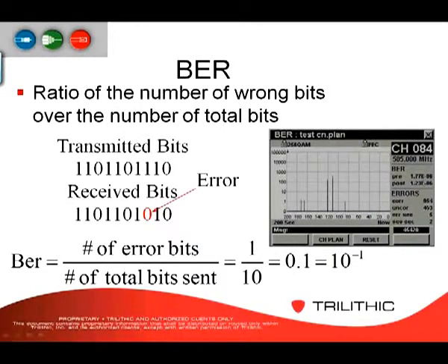Bit error rate measures how often symbols are pushed into the neighboring symbol territories, causing these symbols to be misinterpreted. Remember I talked about earlier that whenever a bit falls outside of the decision boundaries, it cannot be interpreted properly. That's what adds to your bit errors.